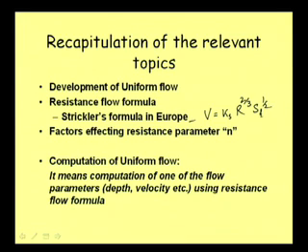That formula is called the Strickler formula, and as you can see, it is just similar to Manning's formula. If I write V is equal to 1 by n R to the power 2 by 3 Sf to the power half, then you can see this Ks is nothing but 1 by n.